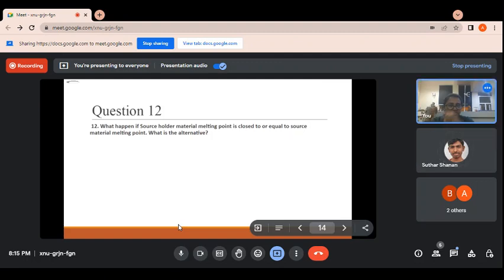Here you have to notice the temperature. I think you have to focus on the temperature. What is the temperature of soft bake and hard bake for the SU8, and what is the temperature for hard bake and soft bake for the positive and negative photoresist? Ma'am, if you watch the week 4 lecture, the same SU8 as you mentioned, soft bake is 65 degrees and then hard bake is 90 degrees. After that the photoresist development, and again you bake at above 125 degrees Celsius. Yes, this is the procedure that I have mentioned in the week 4 video.